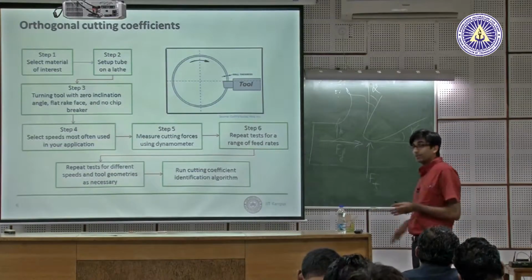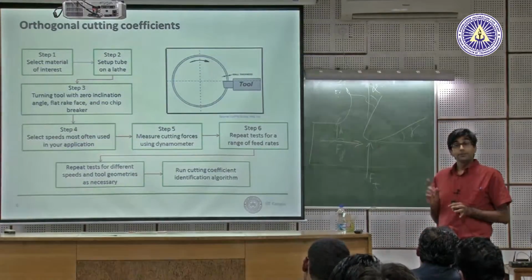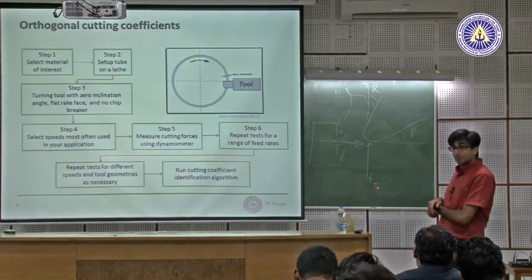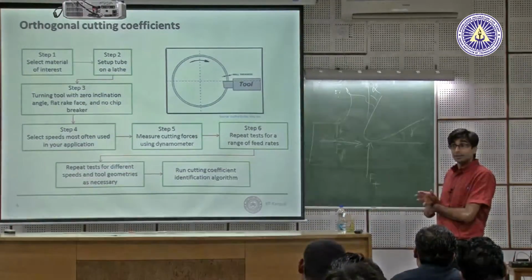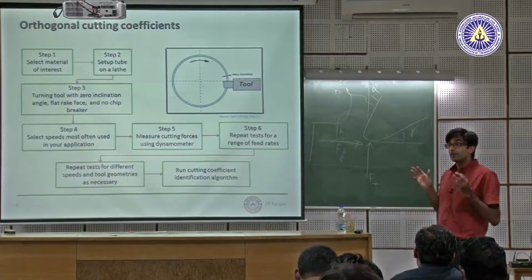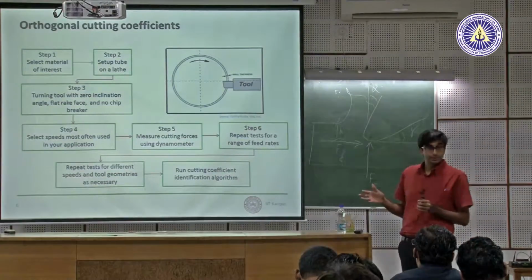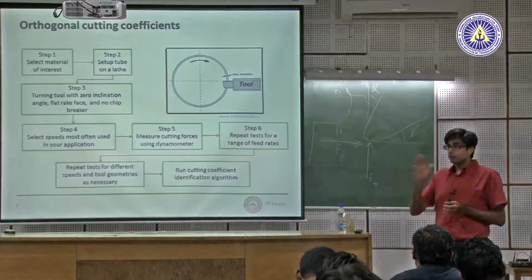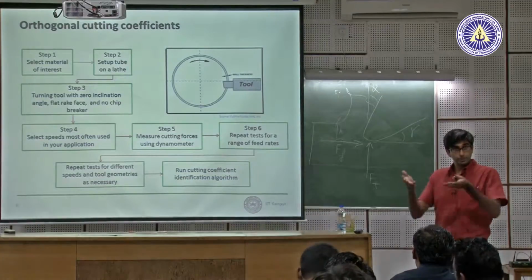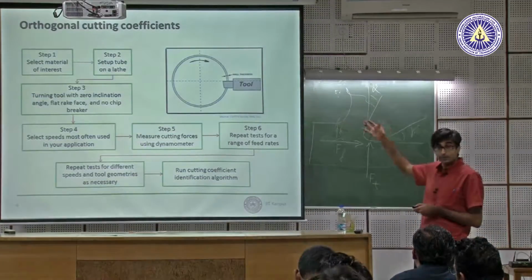So a dynamometer just measures forces, and it measures forces not as FT and FF, or tangential, axial, radial. It measures Cartesian coordinates, x, y, z. That is why we did all those transformations in Cartesian coordinates, because that's what we measure. We can't see these FT, FF directly.